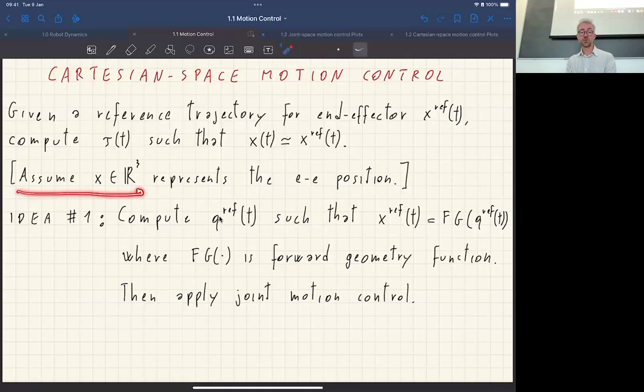So you care about positions, which is 3D, and orientation, which adds another 3 degrees of freedom to your so-called task space. But if we introduce orientation, then we need to deal with the whole problem of working with quaternions and the fact that the derivative of the quaternion is not the angular velocity. And so things become a bit more convoluted.